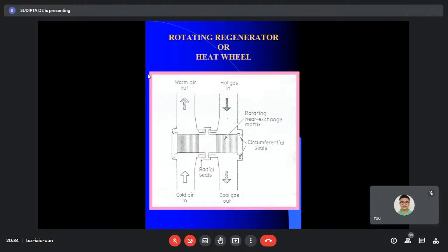Now, the recuperative heat exchange, from the viewpoint of contamination, is absolutely free, because the fluids are not coming in direct contact. But that can cause some depositions, which we call scaling formations, etc. These are separate problems, also under the engineering issues, of how to clean those surfaces. The chemical engineers and mechanical engineers always work together regarding these issues, and these are also very active areas of industry research and activities.